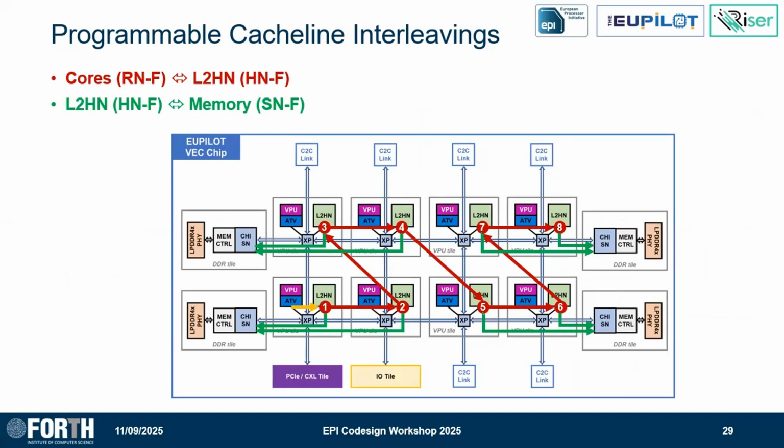Yes. Generally, the 2D mesh has certain good properties, but if you look at their capabilities, they depend on the traffic pattern. When you go into the uniform traffic patterns on 2D mesh NOCs, the larger the NOC, you start to get a lot of contention after some percent of utilization, depending on the size of the network.